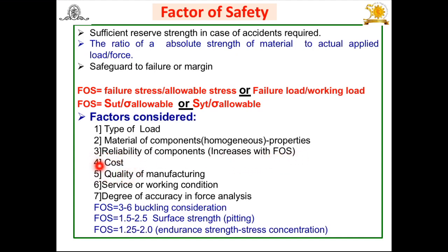Then cost is also important. If we are going to take the value of FOS more, that means the cost of the element is also more, as the dimension of that product or machine element or system is also going to increase.